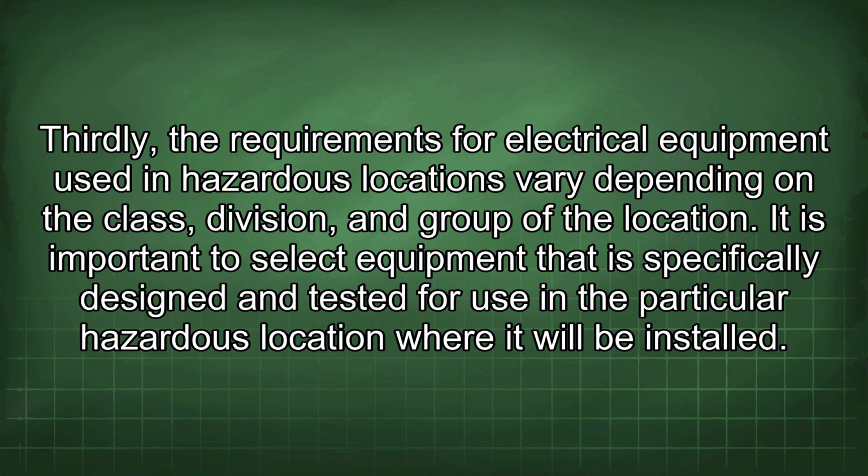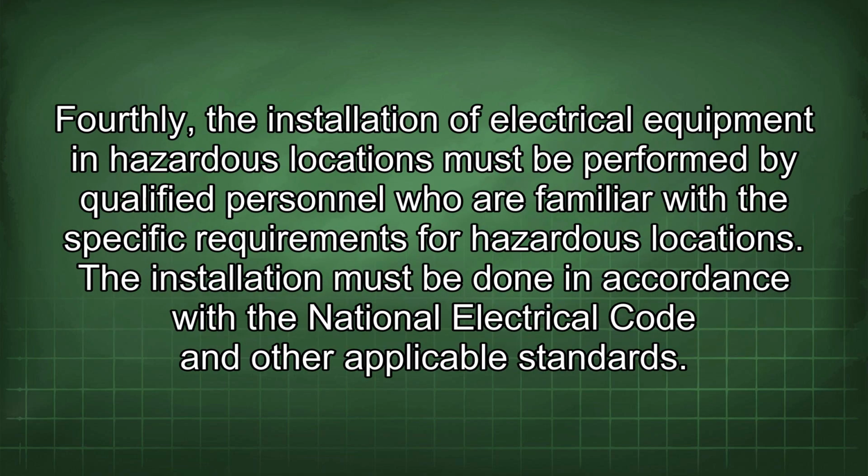It is important to select equipment that is specifically designed and tested for use in the particular hazardous location where it will be installed. Fourthly, the installation of electrical equipment in hazardous locations must be performed by qualified personnel who are familiar with the specific requirements for hazardous locations. The installation must be done in accordance with the National Electrical Code and other applicable standards.